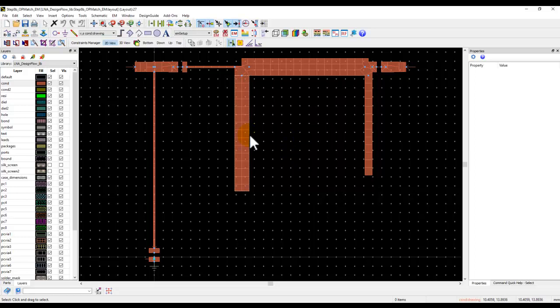All right, so here also on the output side, you can see I have a biasing network, stability, and this is my double stub matching network. And here I have my coupling capacitor, and then finally the output port. And again, you could squeeze the size by changing.